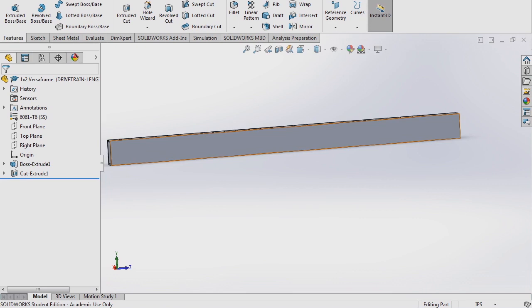What this does is, if our robot is driving in the forward direction, our robot is going to rock onto and lean on the front 4 pairs of wheels. So it'll only be driving on these front 4 pairs of wheels, and our back pair of wheels will be slightly in the air, but not making contact with the ground. Same thing if our robot moves in the reverse direction. Our robot will be leaning on the back pair of wheels, and the front pair of wheels will be up in the air. So at any given point, there are only 4 wheels in contact with the ground.